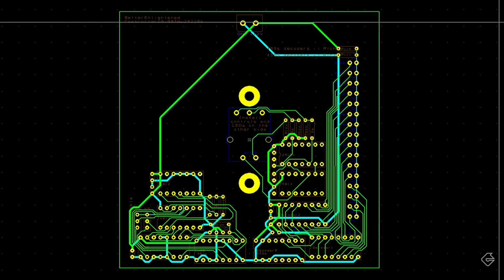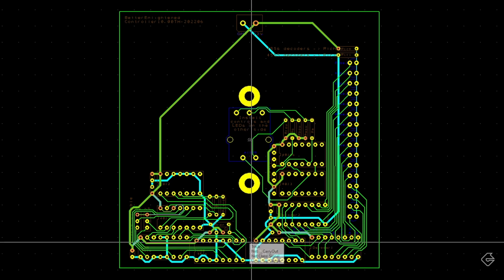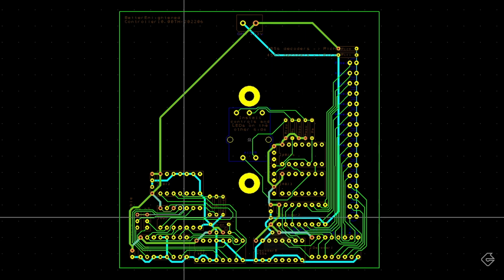So now if I highlight the net, you'll see that the 12 volt connection is mostly connected. There still is a gap in this net and you can see it right down here. This is isolated from this side. I'm not going to worry about that right now. We're going to connect them up a little bit later. For now, let's continue adding the components.